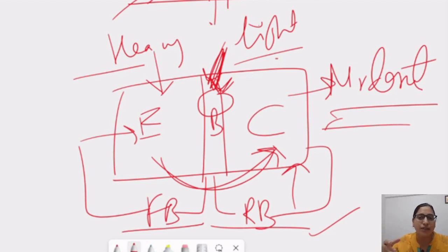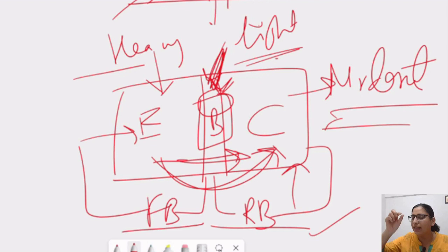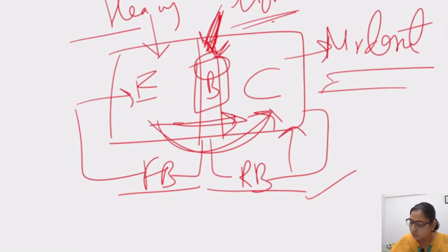So energy is dissipated as heat and so on, but the existence of these charge carriers will be stopped. So to reduce the recombination process, the base is lightly doped and very thin. The layer is thin so that the charge carriers will easily move from the emitter to the base. Okay. So this is the basic construction diagram of the emitter, base, and collector, and a little basic understanding of these.